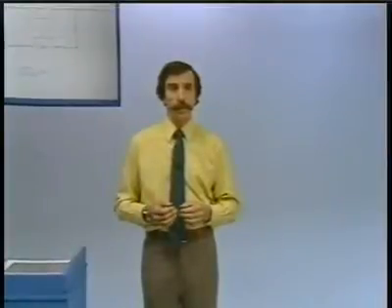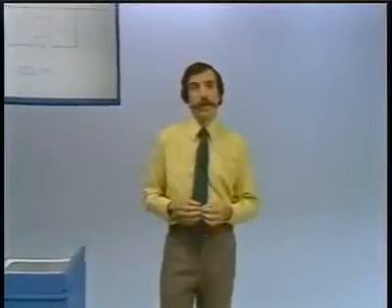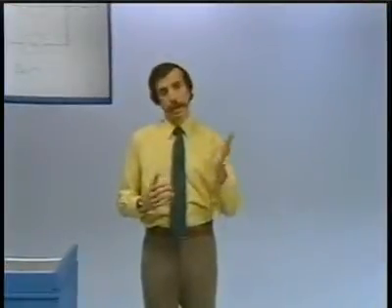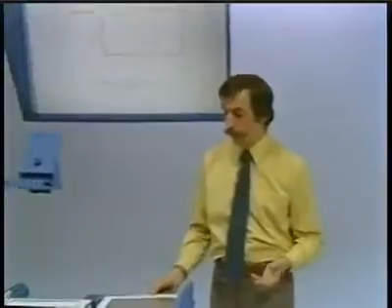And we want to choose the dynamics in such a way that the system ends up being stabilized. Well, I think the thing to do is just simply begin with what would seem to be the most obvious, which is a simple measurement of the angle. Let's take the angular measurement, feed that back, let's say through a potentiometer and perhaps an amplifier so that there's some gain, and see if we can stabilize the system simply through feedback which is proportional to a measurement of the angle, what is typically referred to as proportional feedback.